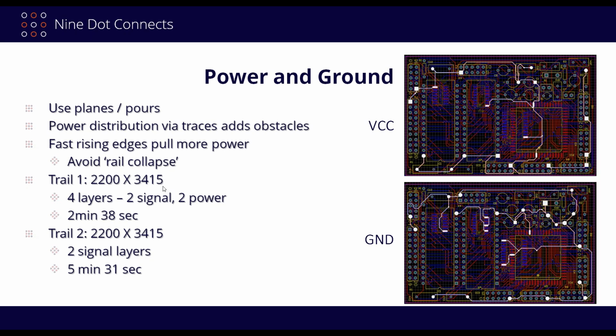Okay? For example, you may say, well, I'm not doing high-speed design, but definitely in high-speed design, you want to make sure you have ample power or ample copper where your power is going to be, so that if a signal is being sent out, the pushing of that signal out, because it draws a lot of current, doesn't drop your rail or your voltage down.